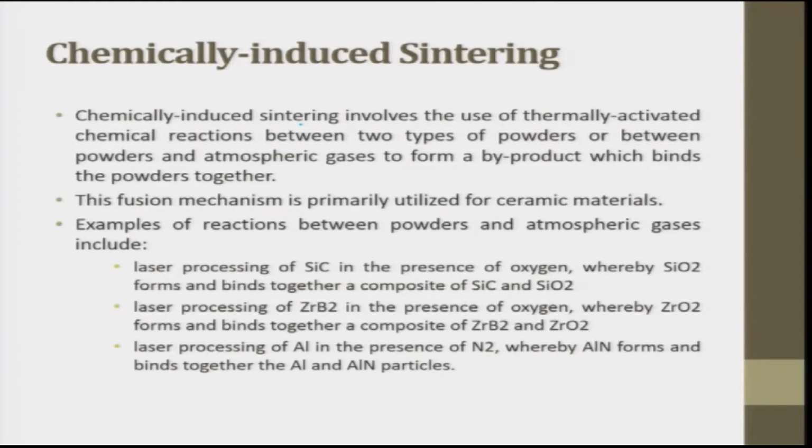Chemically induced sintering. Chemically induced sintering involves the use of thermally activated chemical reactions between two types of powder, or between the powder and the atmospheric gas, to form a byproduct which binds the product together. In a very simple fashion, such that you can understand.